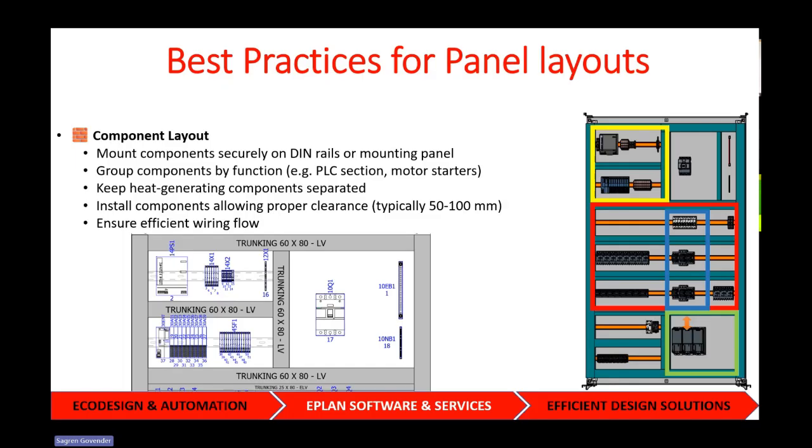So you want to have a nice wiring flow in there. So it's best to look at the schematic drawings and lay your panel out so that you get a good wiring flow and you use as few conductors as possible.